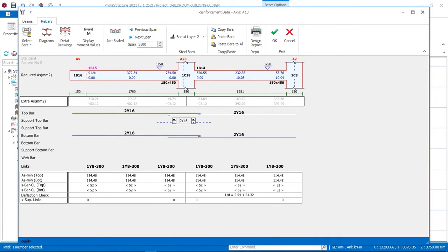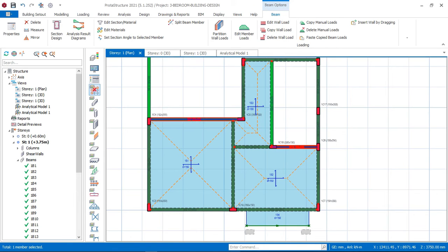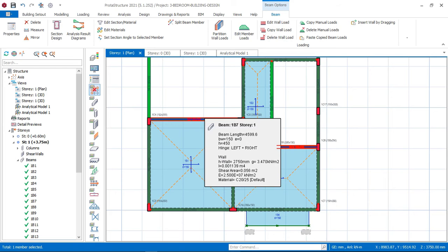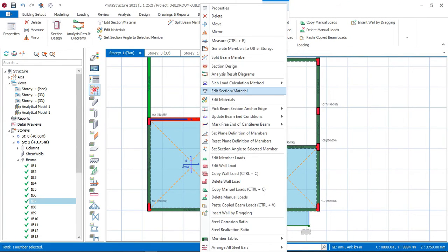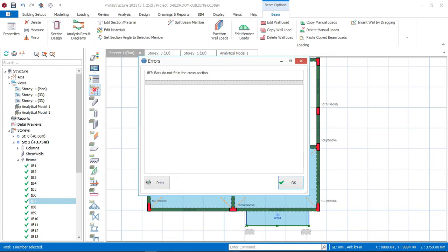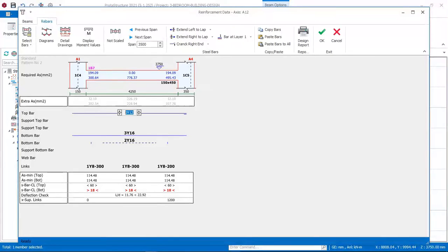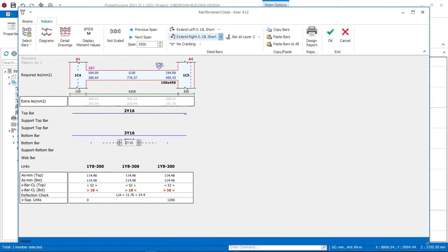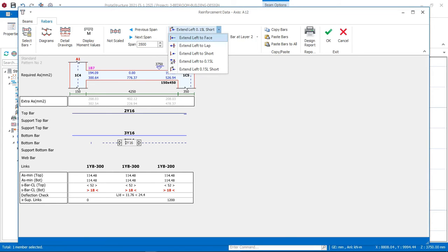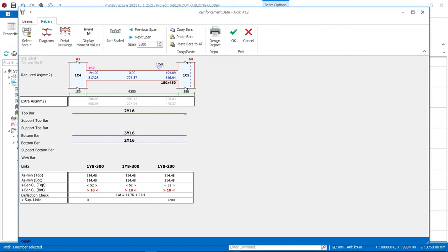So this is also okay, and I'll click on OK, because most times if you cannot perform it very well during the design, and with your experience you can now perform it, you can show it very well on your detailing. Okay, so right now we'll just go and click on OK here, and then make this diameter 16, not 12, and then lap this to the support, and also lap this also.